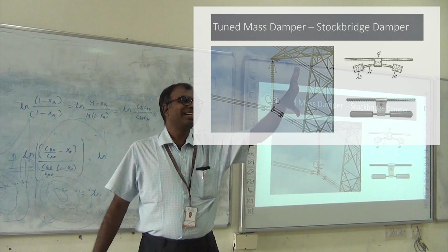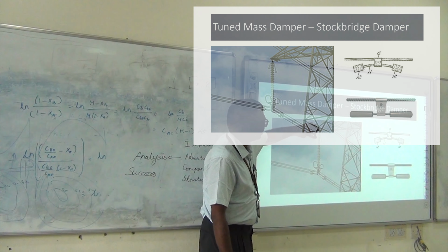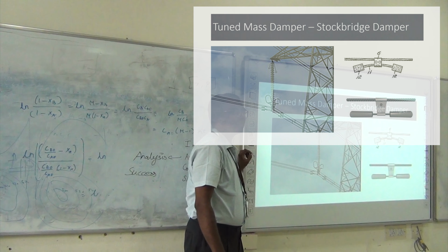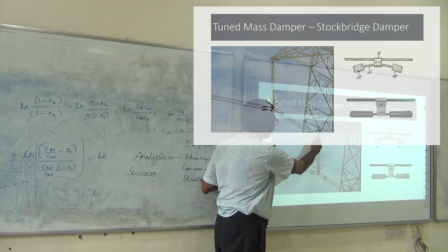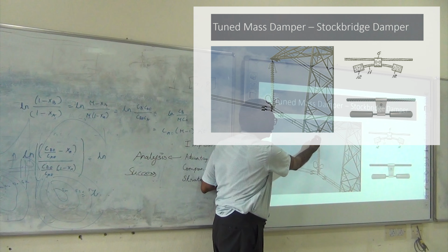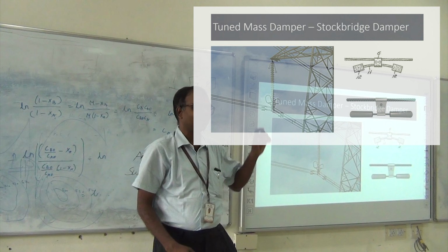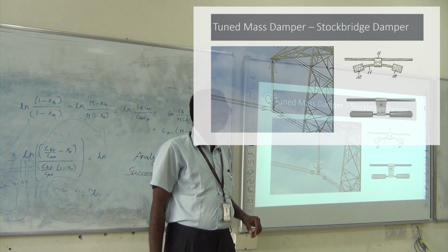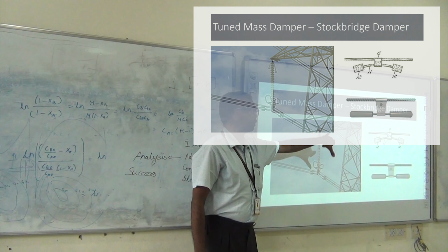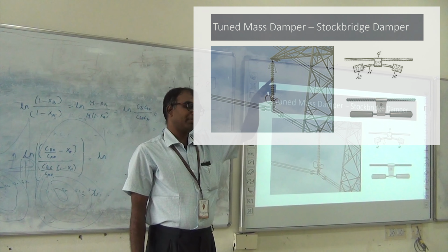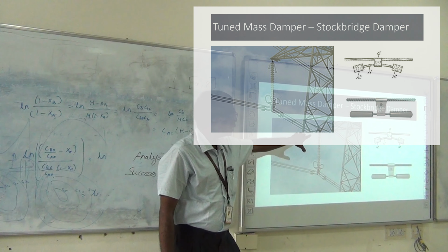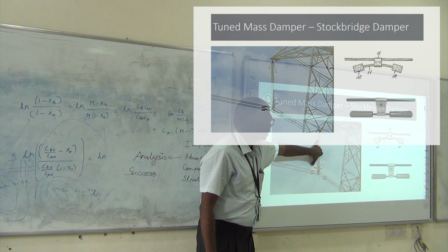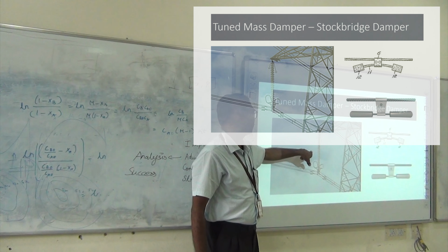Okay, don't worry. This is nothing but two sharp points which we have. In the event of a lightning strike, it is designed so that an arc is formed between these two points. I'm forgetting the name of this protection system. So the insulator will not fail. When a very large voltage is applied, even the insulator can fail and it will start to behave like a conductor. So to protect the insulator, these points are kept.